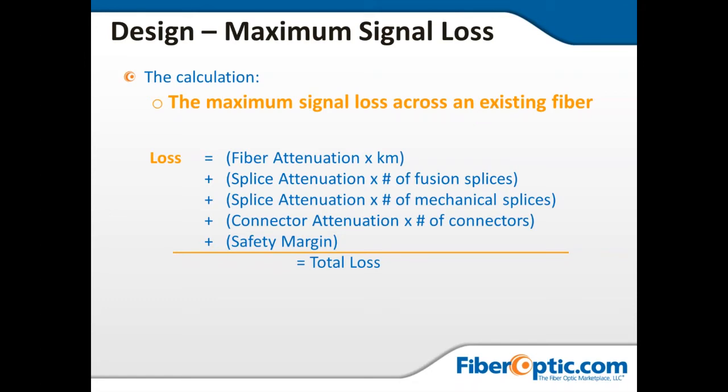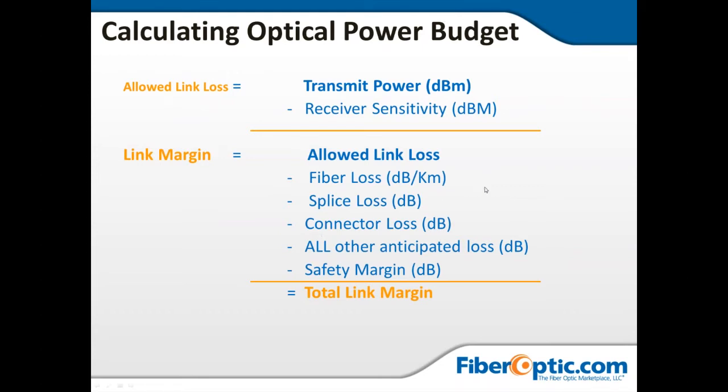And then the last thing to think about is the safety margin. Commonly it could be 3 dB. In essence, all we're doing is adding the sum of the parts, and we're going to get a number. So we can very easily, as cable designers or outside plant, easily calculate what our physical plant will eat up. Now that means that I know that number sitting at my desk. So the average is a very old and simple concept that you see allowed here.